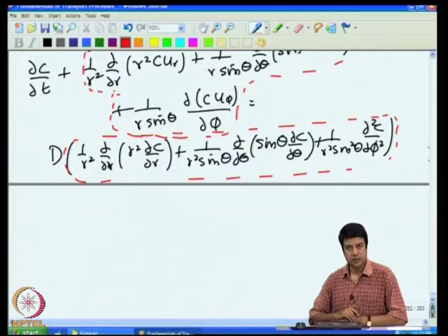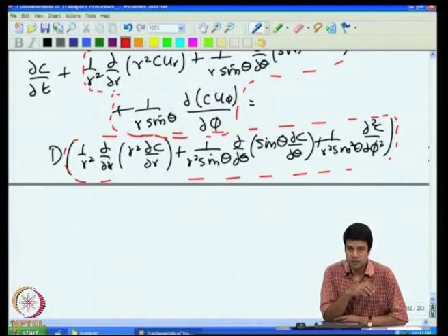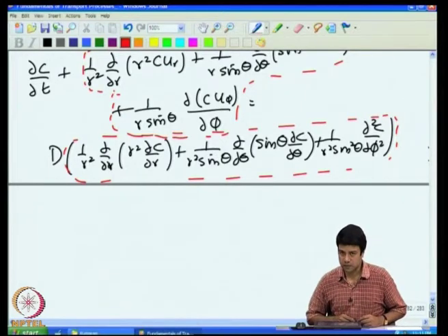For those special cases, we had devised various techniques to solve the equations. The first one, if you recall, was a similarity solution for the transport due to the instantaneous motion of a flat plate for momentum transfer, or the instantaneous heating of a flat plate for heat transfer. In that case, we had transport from a flat plate into an infinite fluid, with no length or time scales in the problem, and we were able to reduce the problem just based upon dimensional analysis to just one similarity variable, z by square root of alpha times t, or z by square root of nu times t.